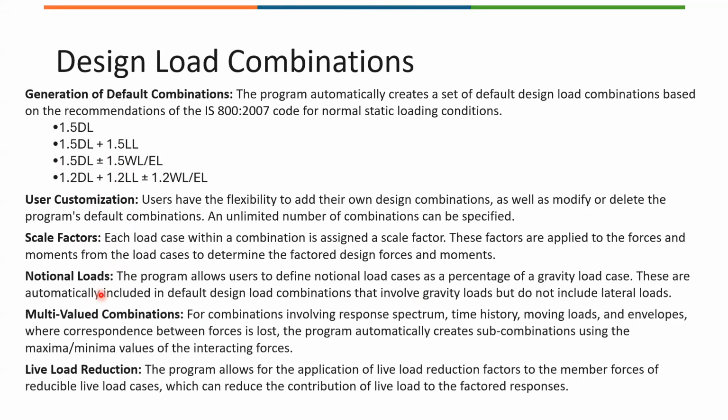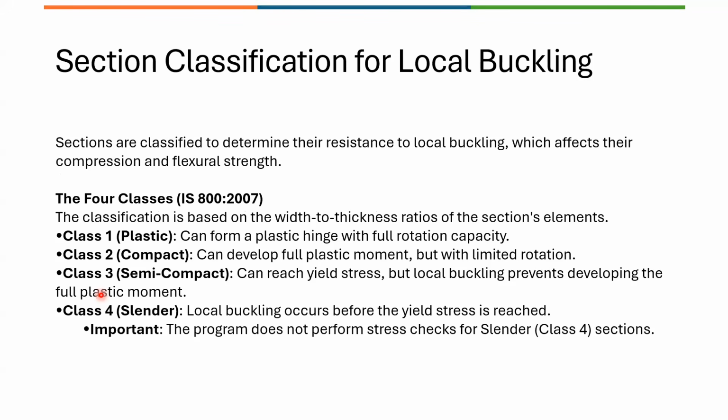And it also has the live load reduction. The default, you can control that based on the code, or you can specify it as a user-defined reduction factor. So all of this is coming into the design stage. And whatever you see from the analysis forces will be there, but for the design of the members, the program will involve all this, and you'll get the final design forces that you will see in the output, which may not match the analysis forces.